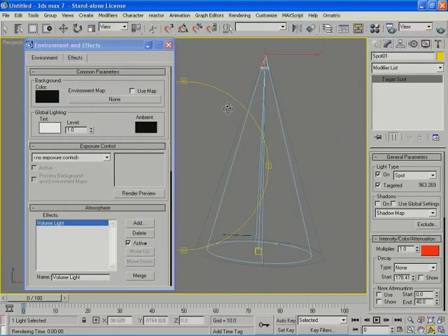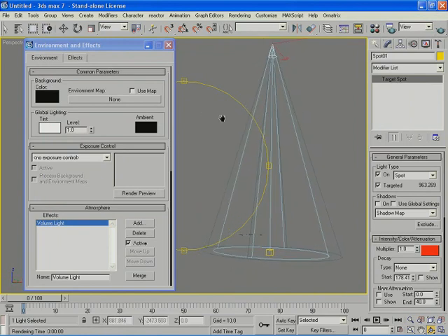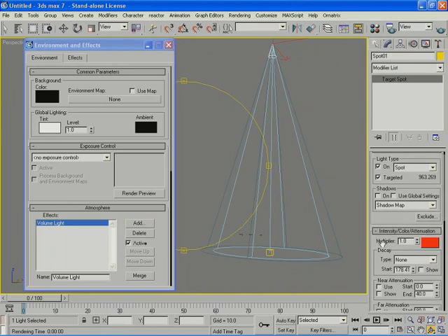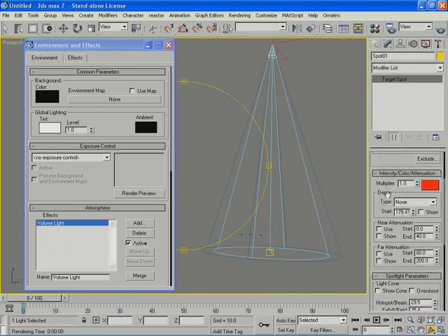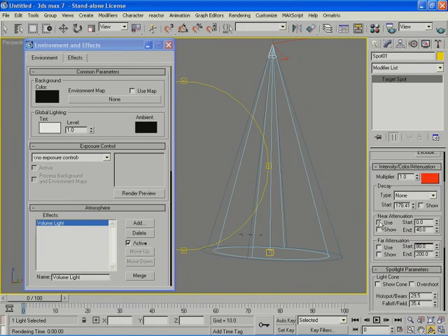So here I have to use attenuation to attenuate the extent of the light according to some values that I specify manually, which have nothing to do with the intensity of the light according to the way it decays with distance. So this is a manual way of changing the light. The other one is physical. I'm going to discuss far attenuation first, and then try to figure out why I would use near attenuation, which is not very common in life, because lights always shine from their source. You don't ever have a light that doesn't shine around its source but shines later. This is what the near attenuation does, but we're going to find a way to make it useful for us.